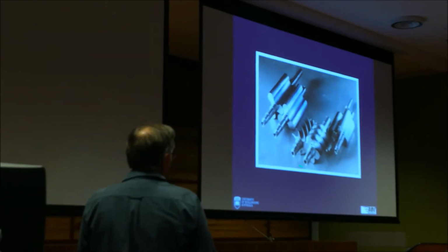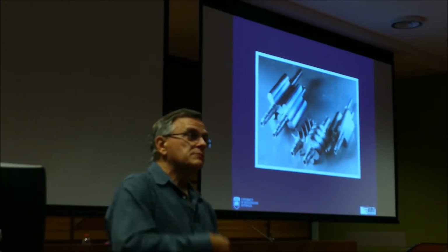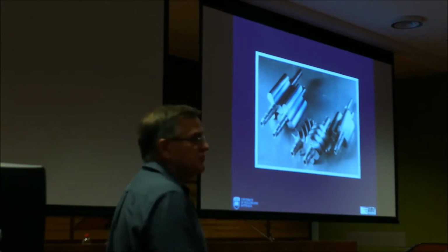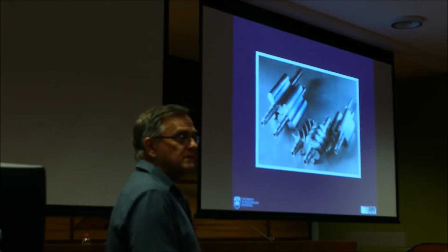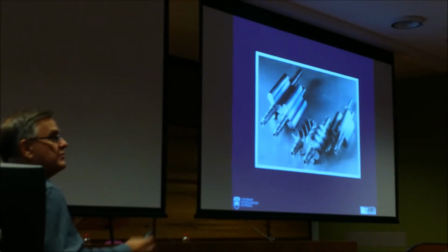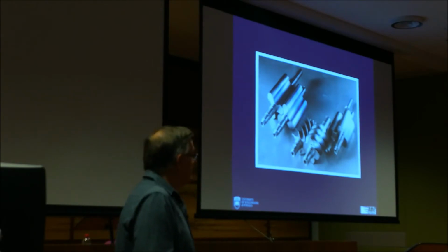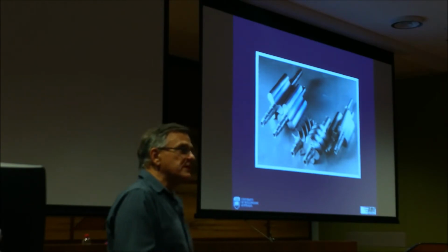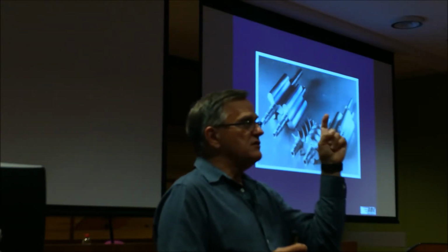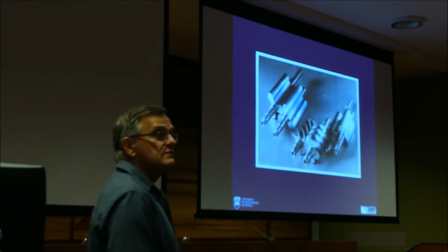Anyway, the traditional type of compressor is reciprocating or piston type, compressing the air before it discharges. They're still around, but the rotary screw is far more efficient, so you'll see them more prevalent these days. But when you get to really high pressures, you'll go back to the piston type compressor. There are other types of compressor elements, what they call rotary tooth, where it squashes the air before it discharges, like a tooth that comes around and squashes the air. So there are different designs.